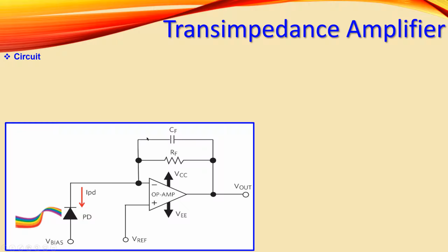The feedback is formed by the capacitor and the resistors. This will be discussed shortly in great detail. And we have of course the output, which is a voltage. So the input is current and the output is voltage, so the volts divided by the amps is the impedance, just using Ohm's law. That's why we call it a transimpedance amplifier. So that's the circuit. What you see is that it converts electric current to voltage. It is also called TIA for short.